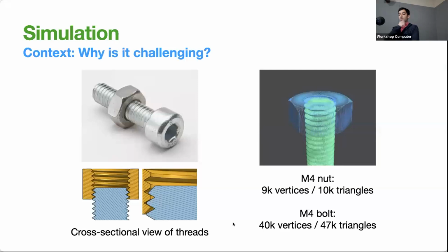To some extent, you might wonder, can't we simulate contact-rich interactions already? We certainly can, but there are limitations. Consider the canonical problem of simulating a nut and bolt. Despite the ubiquity of threaded fasteners across the entire world, it was previously not possible to simulate them faster than real time. There are finite clearances between the threads of the nut and the bolt, which can allow the nut to move with 6 degrees of freedom.